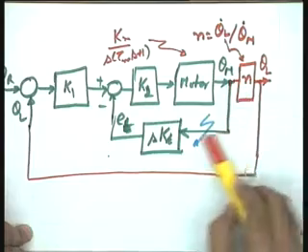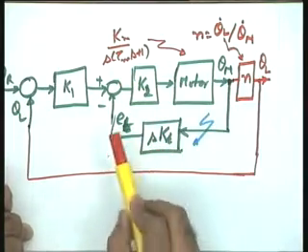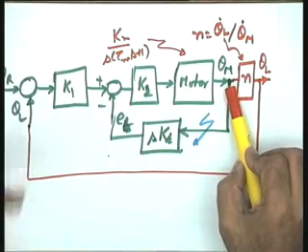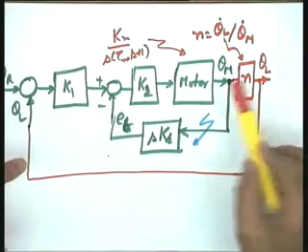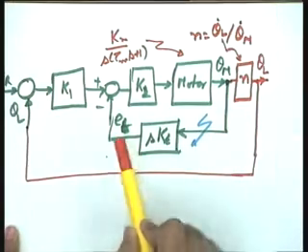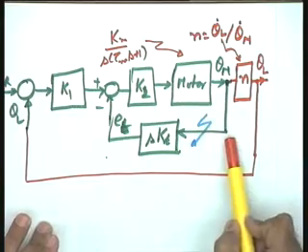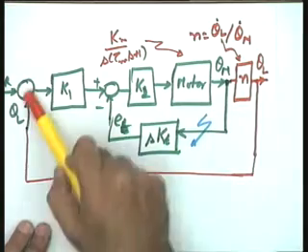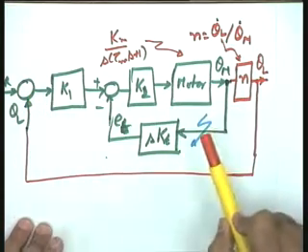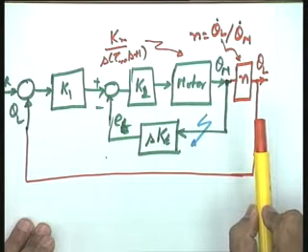You just see that there are two loops. One loop is through the position and the other loop is through the velocity. That is, you can say as if this particular loop is the derivative of the position. So it means as if in addition to the output signal, you are feeding back the derivative of the output signal as well. So if this derivative is removed, if only the output signal is fed back, what will happen to this particular system? So there will be more hunting.